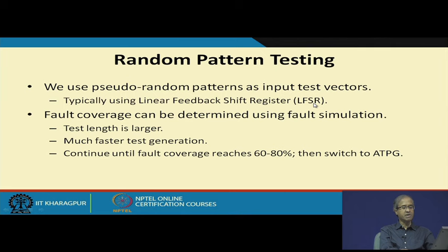So, we can use an LFSR, a very simple hardware structure. Say we generate 1000 random patterns, and using fault simulation we can find out what fault coverage those 1000 random patterns give, that is, what percentage of faults are getting detected. If our fault coverage has reached an acceptable value, we can say, let us use this many patterns. I am giving an example.